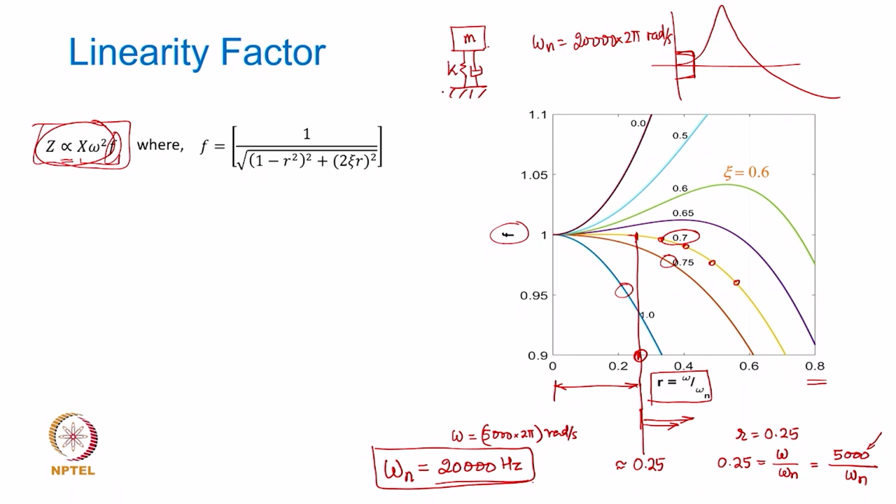That the K should be large enough, right. So, this is what the design is, and then of course, for making sure that the C should be such that the damping ratio is 0.7. Fortunately, these piezoelectric materials do have a good damping property or a damping factor, and so that suffices.